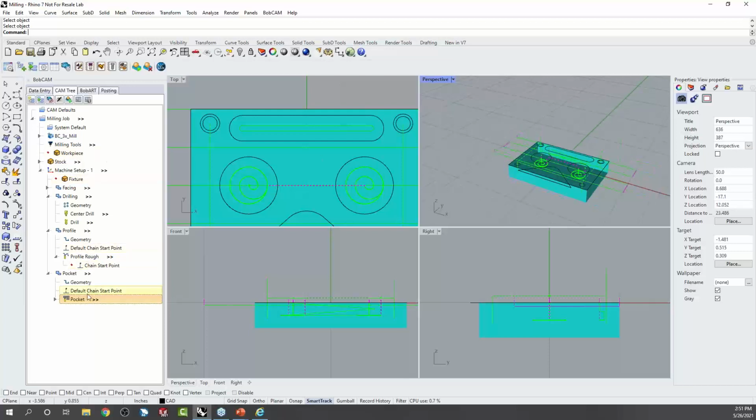So again, being able to use templates is a fast and easy way to reuse settings, because it's all in the details: depth of cut, width of cut, stock for finish, speeds and feeds, the tooling that you're using, the zero position, your initial stock prep. These are things that vary from shop to shop. If you can come up with standard workflows and procedures, it can really speed things up for you.